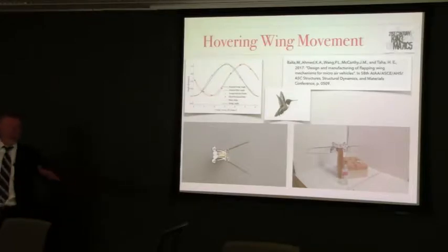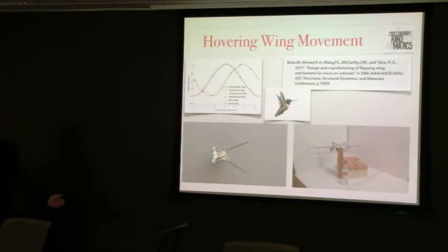So when you're swinging back and forth, you want to change the pitch of the wings so that you get lift. The way the nano hummingbird adjusted the pitch was by the material properties of the wing itself. They spent quite a bit of time determining material properties that would take the right shape when the wing was moving in an air environment in the proper way.